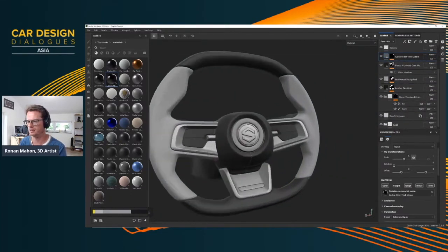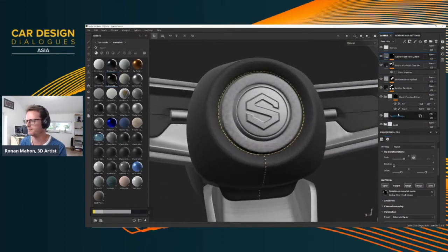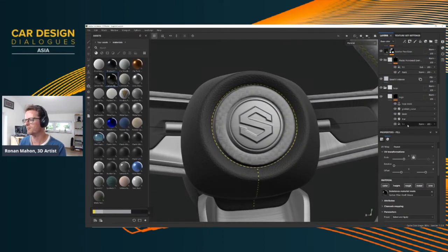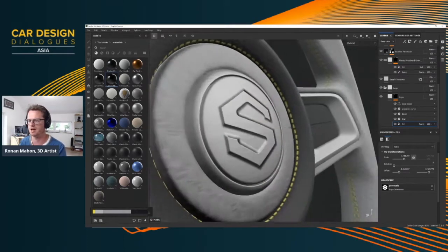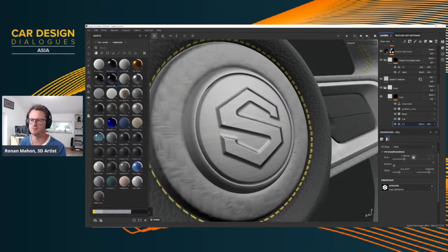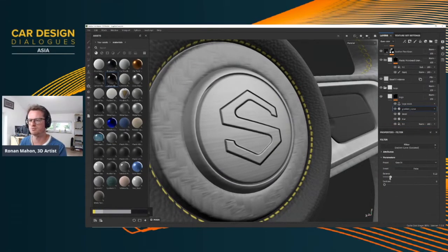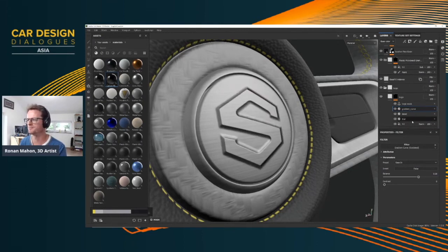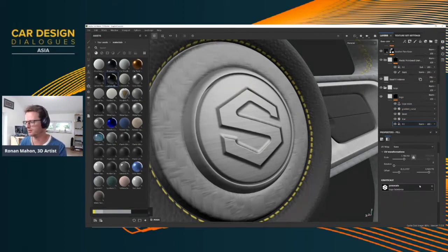And finally, we've got our little logo, which is the Substance S, and it's sort of being embossed out of the metal. Now, the power of Painter, you can sort of say, well, this is all just being driven by a simple grayscale logo. It's a black and white image. It doesn't actually even have any of this beveling on it, and that's all being controlled by some parametric options here. So I can interpret how this lovely black and white image is being used, or I can just come along here and, you know what, I'm going to swap it out.